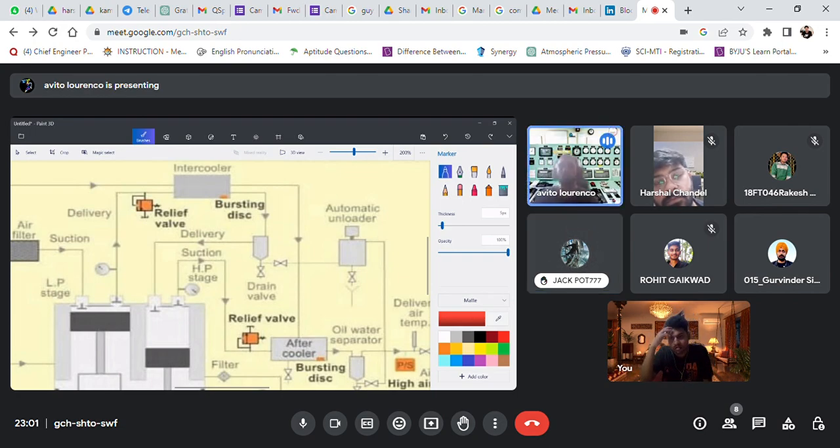So this is a very good difference: in the pump's case, the discharge and inlet are the same fluid, so I can just feed that excess discharge pressure to my suction side. But in the case of the intercooler where the bursting disk is located, the high pressure is caused by the leakage of air into water. So I'm trying to get rid of the water and air mixture that has leaked as soon as possible. I cannot send it anywhere back. So there is no point in a relief valve.